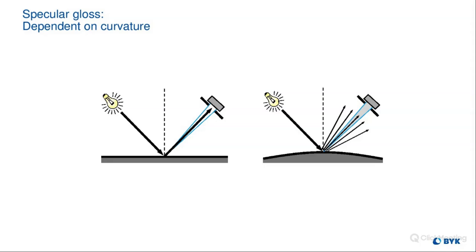But I may end up finding that because of the curvature, I'm able to get around 20 gloss units. Then I can make that 20 the standard, so that whenever I compare parts to parts, I'm always looking for 20, because I know that's visually what I want, but numerically I'm not able to get there because of the curvature. So there are ways around it, and that's one of the methods of doing so.